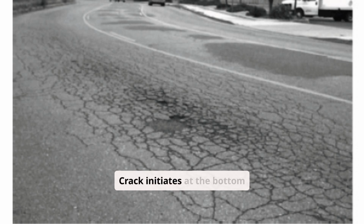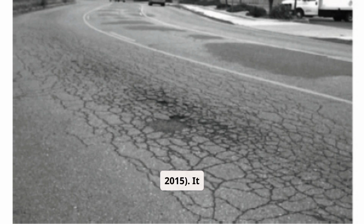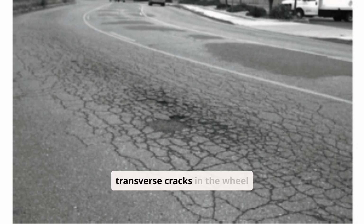Causes. Crack initiates at the bottom of the asphalt layer due to repeated tensile strain caused by wheel loading, AASHTO 2015. It propagates upward and appears at the surface as several short, longitudinal, or transverse cracks in the wheel path and interconnects laterally with continued repeated fatigue loadings, forming many-sided sharp-angled pieces that develop a pattern which resembles the skin of an alligator or the shape of chicken wire. This crack occurs because of thin pavement or pavement with weak base or subgrade, excessive loading, or a combination of these. Other factors such as poor drainage accelerate the progress of this crack.